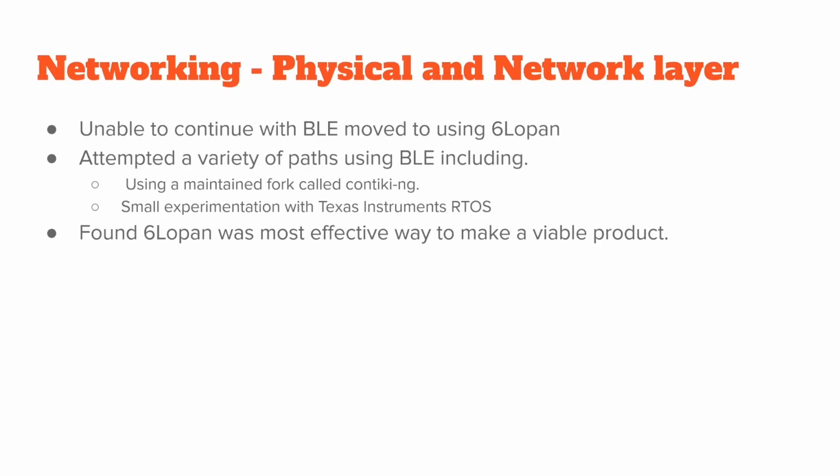The other option was to use Texas Instruments' own real-time operating system. I was able to build that onto the device, but it would have required learning another real-time operating system, and due to time restraints, we didn't pursue that path. We actually just fell back to the 6LoWPAN, given that we're able to reuse functionalities for sending TCP packets back and forth. There was a fair bit of debugging, as I spoke about earlier, in that the RF would drop off, but once we moved past that, we were able to send TCP packets to a client script running with Python scripting.